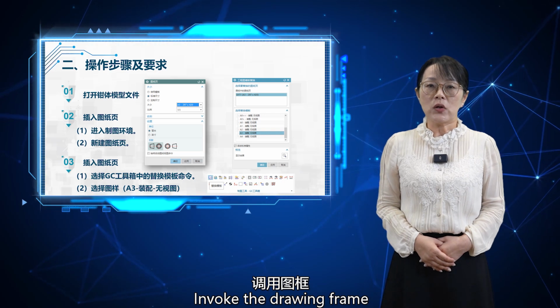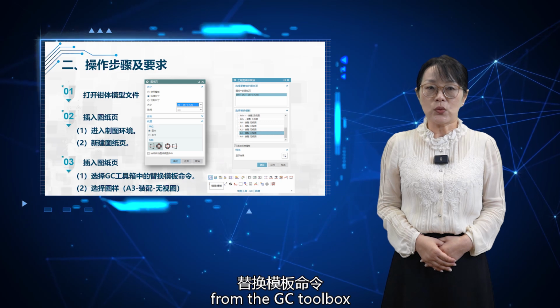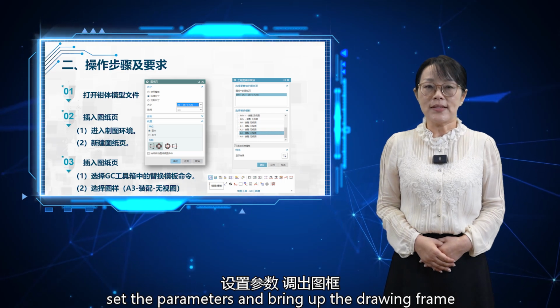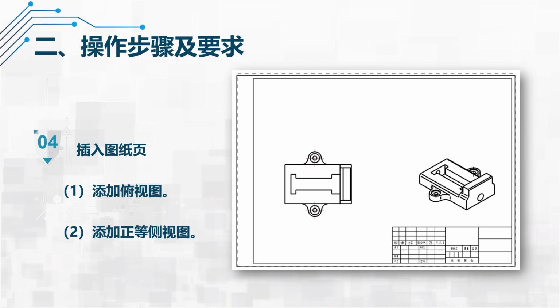Invoke the drawing frame by selecting the Replace Template command from the GC View box. Choose the template A3, Assembly No View. Set the parameters and bring up the drawing frame. After entering the drawing sheet, we click to add the basic view.